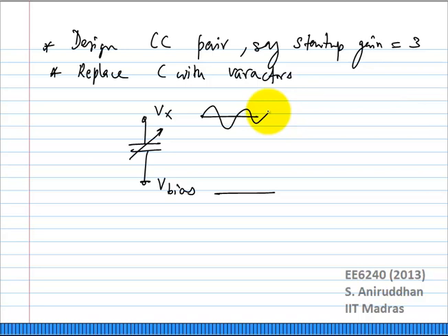What we are looking at is an AM signal. This is a constant phase with an amplitude. This gets converted to the phase of the oscillator, and therefore you get sidebands. So you get what is called AM to PM conversion. And obviously this amplitude varies in a certain manner. The phase and the sidebands of the oscillator will also vary in a certain manner. In other words, if I had any amplitude noise at the output, which I have been ignoring so far, that amplitude noise will get converted to phase noise through this mechanism.